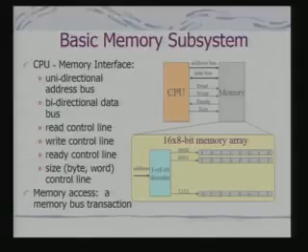So the basic structure or the organization is something like this. I have got the CPU. The CPU is interfaced directly here with the memory. There will be an address bus to select the memory location, and a bidirectional data bus for sending the data to write onto the memory as well as to get data from memory for the purpose of reading. These are the control signals, read, write, as well as this ready signal. If the memory is not able to respond to the request, it may ask the CPU to wait. So that's why another interfacing signal is a ready signal.